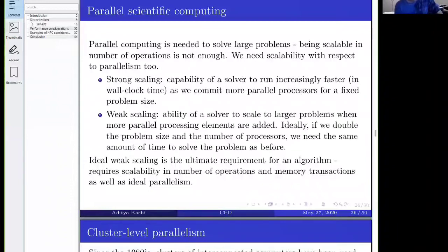For the smoothing, what is the order of RK? Yes, that is a good question. It actually depends on your specific problem. For example, for compressible flows, people who want to use RK typically use 4-stage or 5-stage RK methods, but they are typically not your traditional RK4 or RK5, for example. The coefficients are not optimized for accuracy, because ultimately we are solving a steady state problem. We don't need the time stepping to be accurate. What the coefficients are optimized for is damping the high frequency errors. So there are special multi-stage RK methods that are used for smoothing.